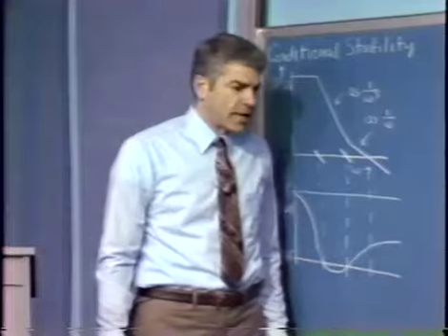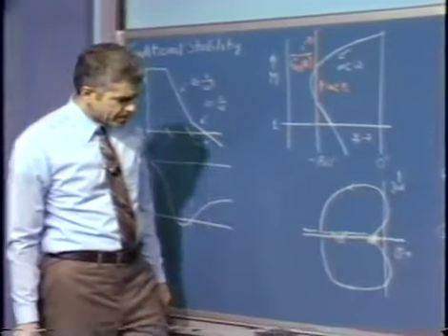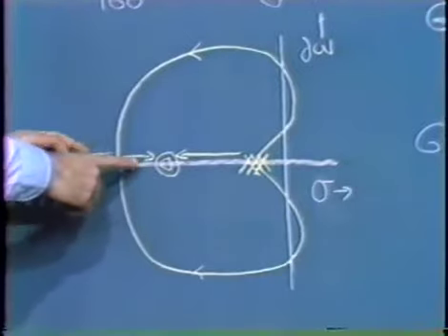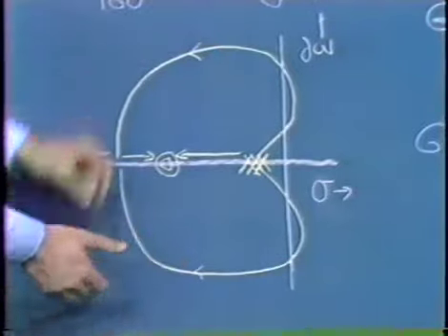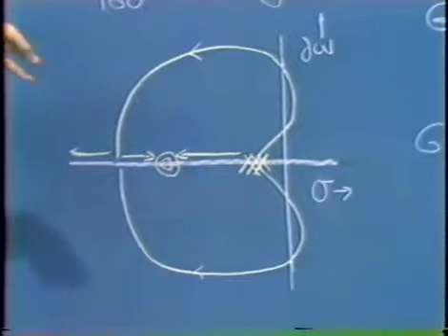Again, we can look at the same process from a root-locus point of view. We assume that we might start out with a system designed so that all of our poles lie in the left half of the S-plane. However, as we increase the amplitude of the signal at the input to the nonlinearity, the loop transmission magnitude, the A0 F0 product, in a describing function sense, drops.